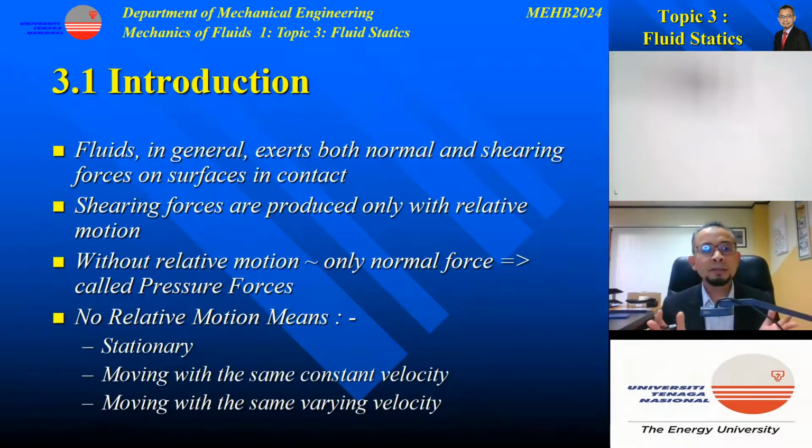Fluids in general will exert both normal and shearing forces on any surfaces that the fluid is in contact with. Shearing force will be produced only when there is relative motion, meaning that the fluid is flowing. Without relative motion, only the normal force or direct force will exist, which is called pressure force.